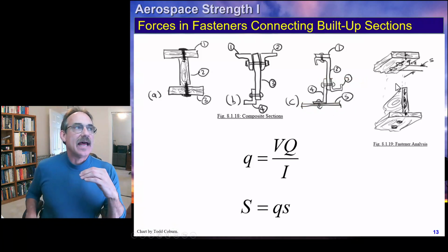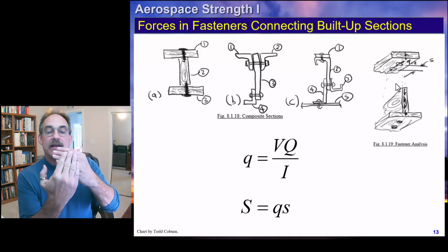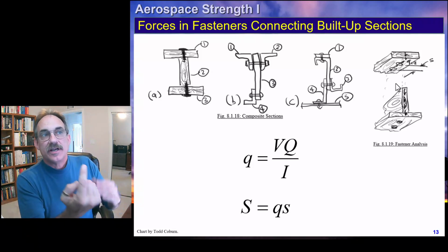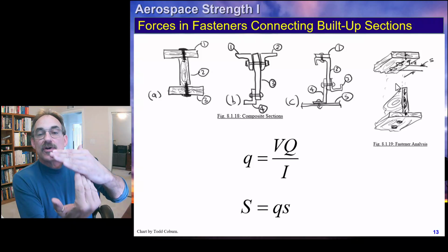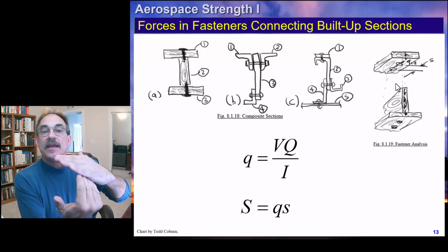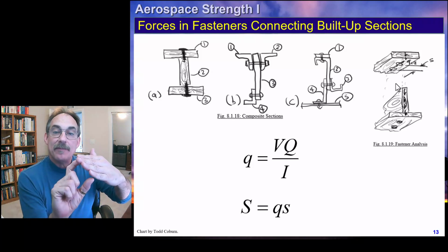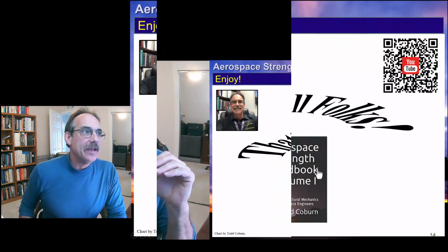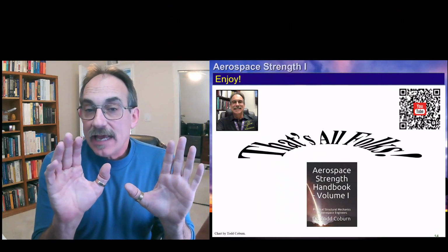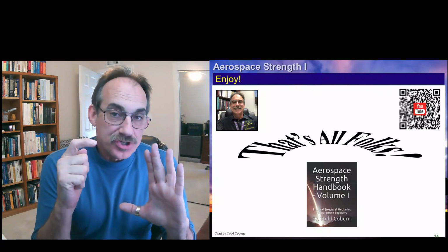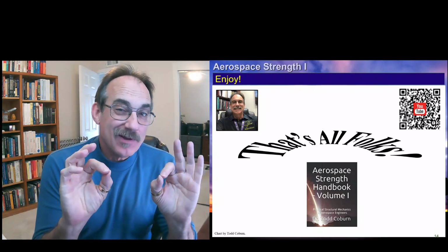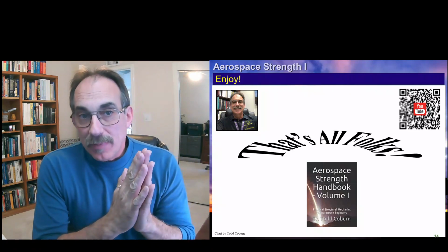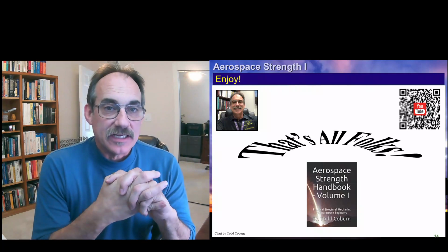This is another little look at that beam. If we had those nails, that first beam, if we split that upper cap off so we can see that spacing of the fasteners through the upper flange, that's that shear flow acting underneath. It's trying to slip the one piece over the other. That shear flow acting like that, multiplied by that spacing, tells how much force develops per fastener. Okay? So that is how we calculate shear flows and shear stresses based on shear forces for beams, sections, cross sections, things like this.